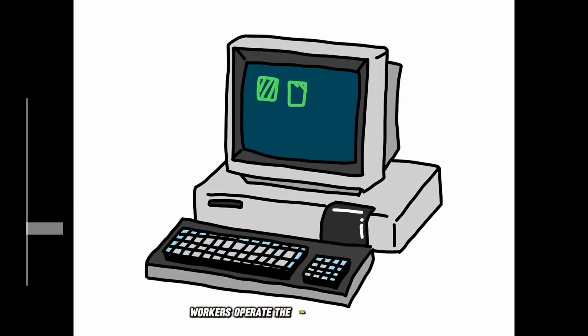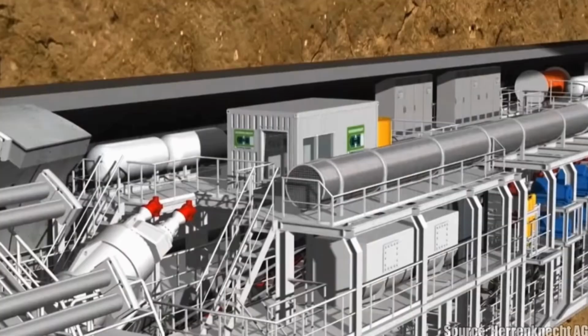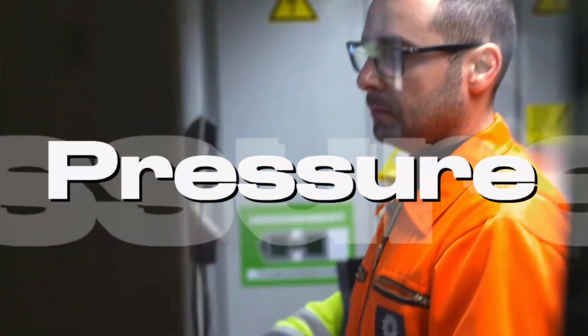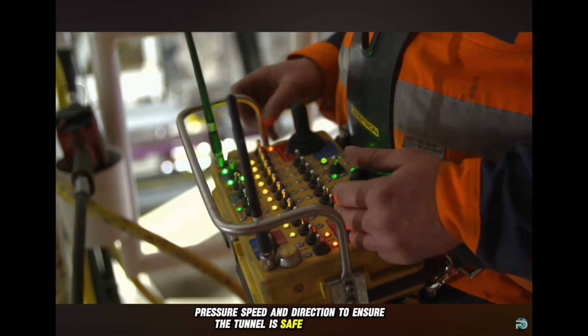Workers operate the TBM from a control room using computers and monitors. They monitor torque levels, pressure, speed, and direction to ensure the tunnel is safe and straight.